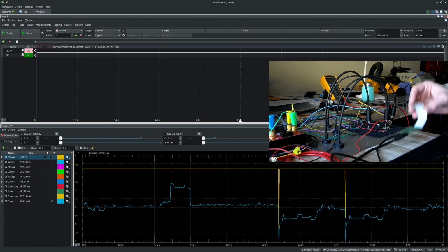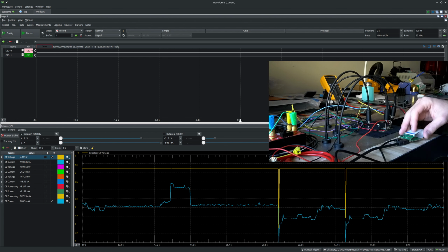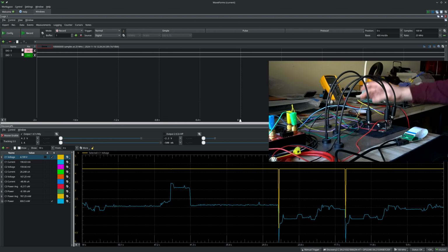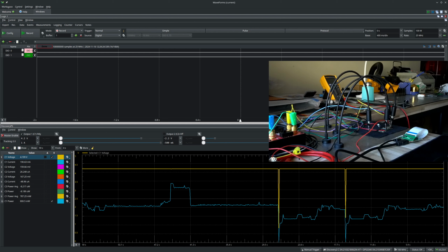But specifically, I wanted to talk about the digital protocol side of things and how these displays are initialized. Since there's often some driver-specific initialization commands that need to be sent over the interface before the display will work in video mode, you either need to ask the seller if they have that sort of documentation or find it online somewhere, maybe in some device trees or info from Linux source dumps that people have published for various phones and such.